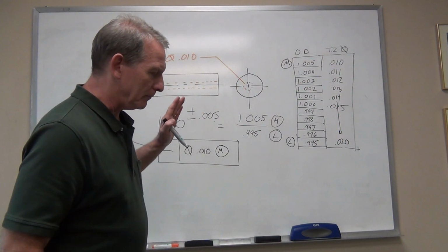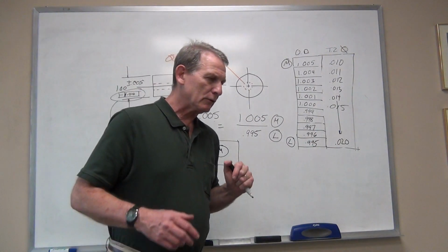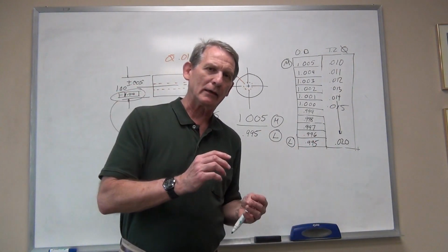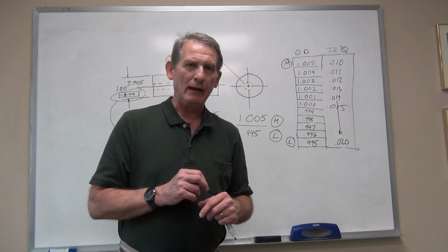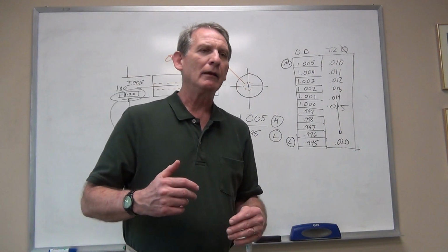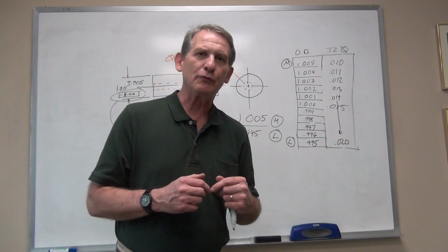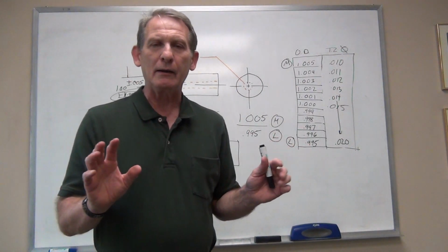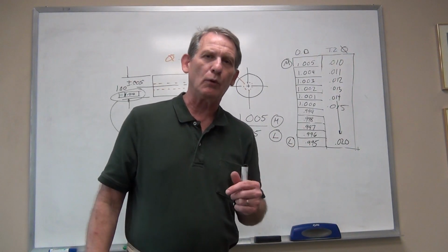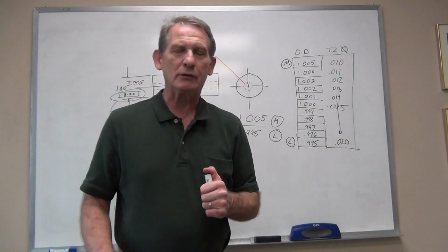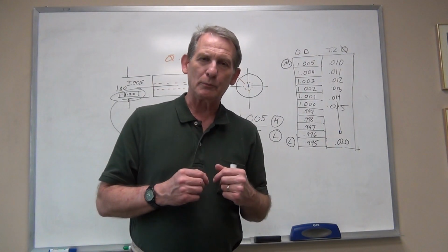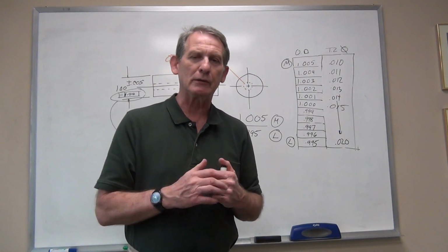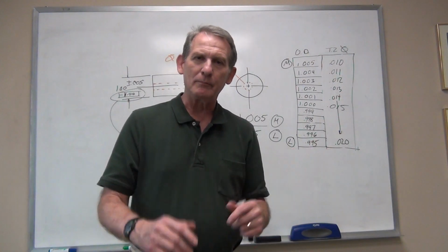This is again a critical aspect to making sure that if you're making two parts in two different locations, when they come together, they will fit. And that adjustment of the tolerance zone is something that you probably have done yourself and never even realized it. When you're trying to fit a piece of sheet metal over a frame and the holes aren't lining up, you open up one of the holes, you have done this. You have adjusted the tolerance zone, the positional tolerance zone in this case, by reducing the material condition. Going to a least material condition in a hole is opening it up.